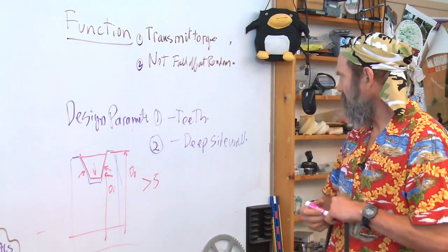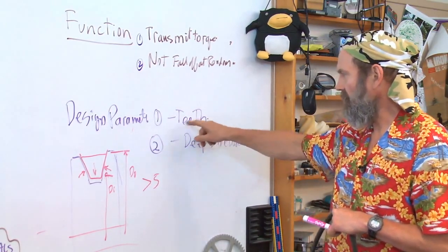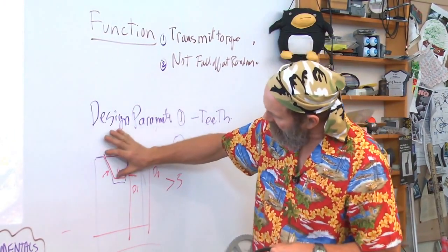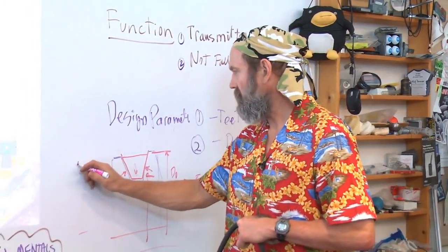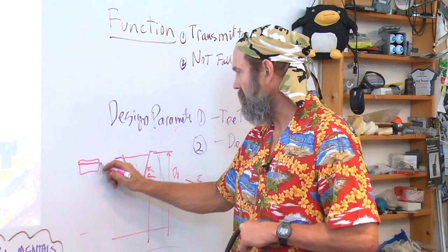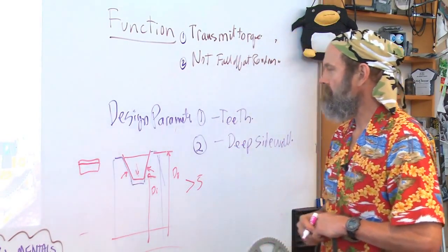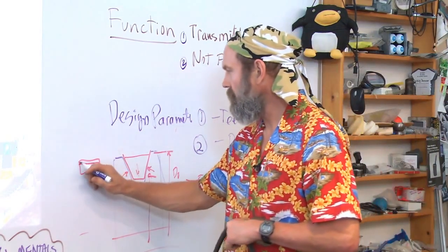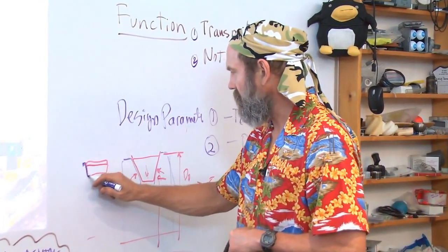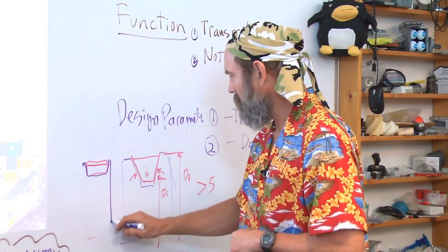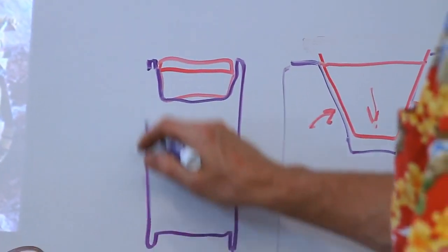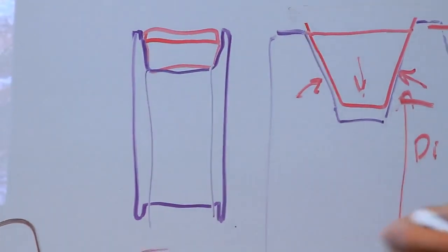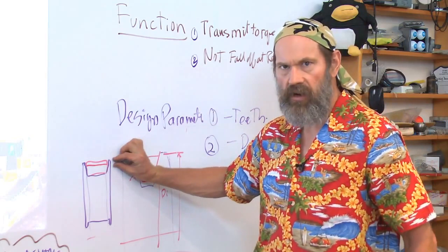But that has nothing to do with teeth, and you have to be really careful about tension. But V-belts don't come off because they've got this deep engagement as compared to a timing belt, which is very thin and then has teeth. And when people try to use timing belts as tracks, and they have these little flanges on the side, which are very small, they're very easy to come off.